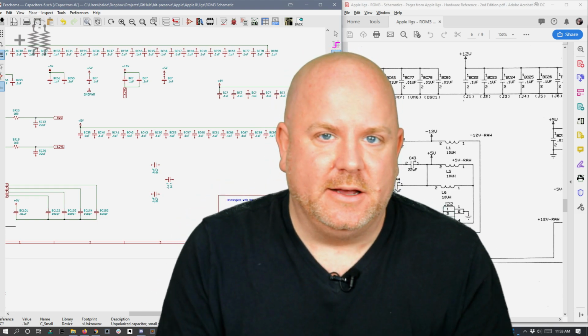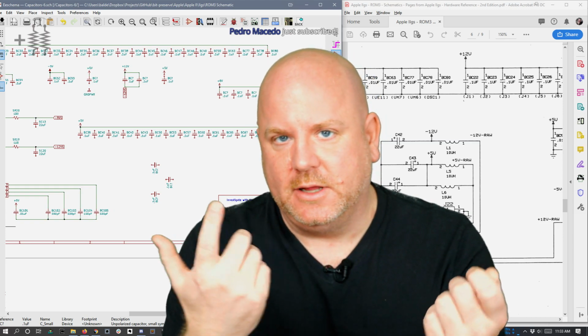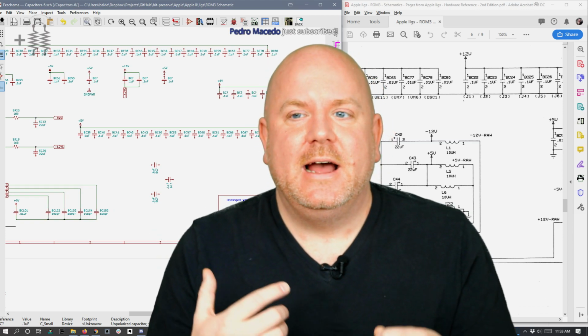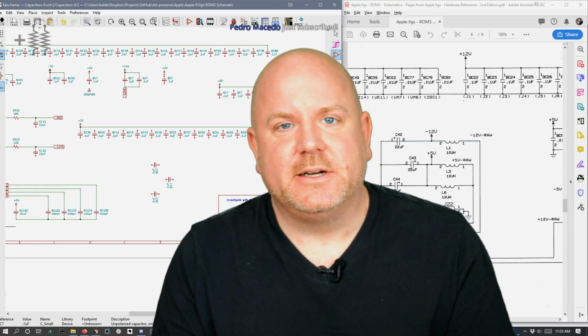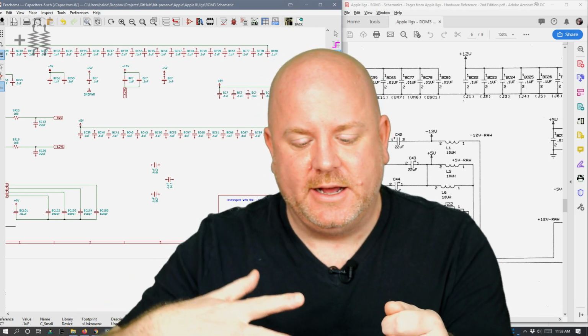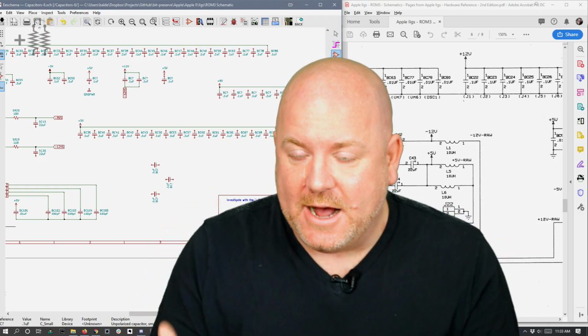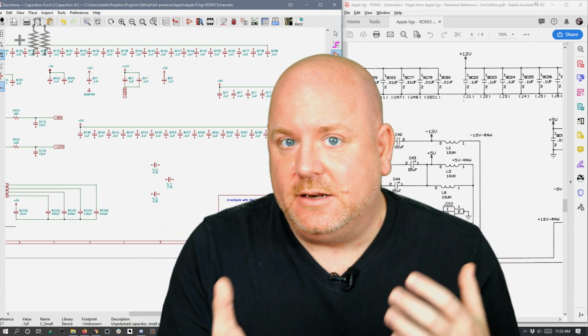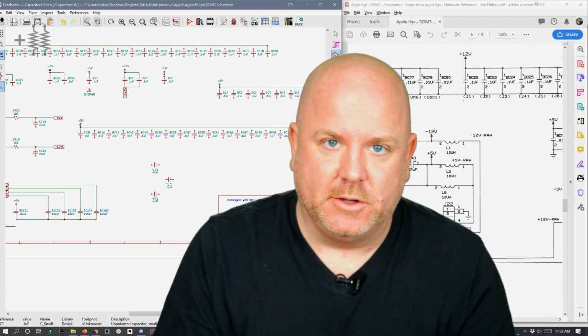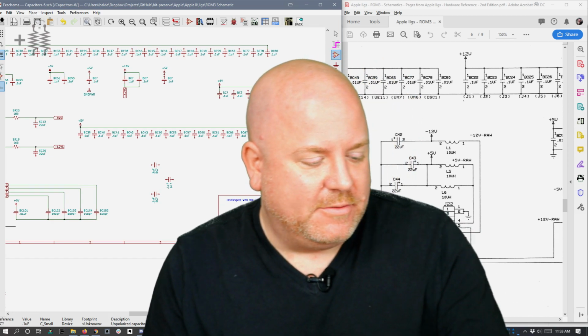And then the same thing with the LEDs, everybody would say, oh, the short leg is the cathode or whatever. And the thing is, I played a dirty trick on every single class. I went in and I cut the legs at an angle so that it was backwards, to point out that it's not always the lead length, that you really should check it with a multimeter. Okay, enough of my lecture.